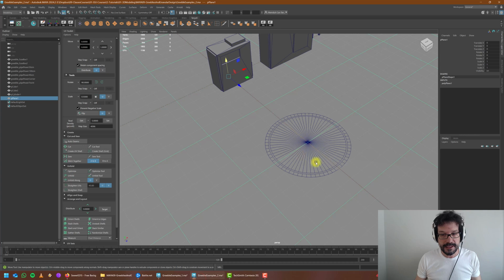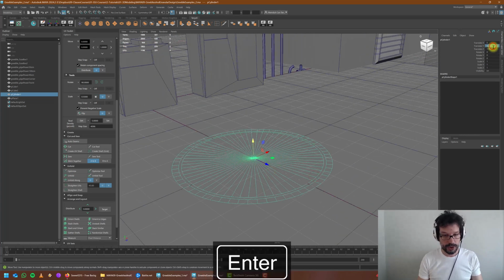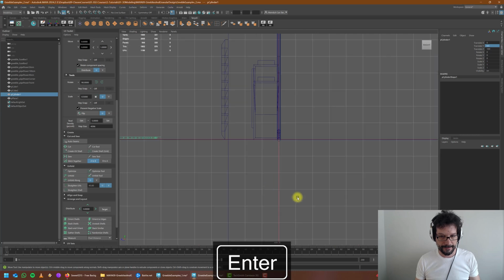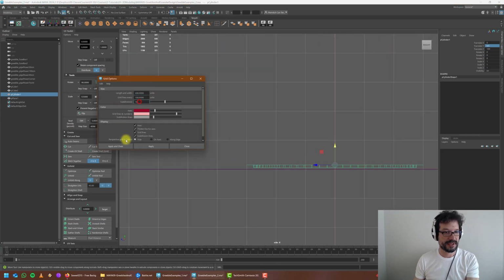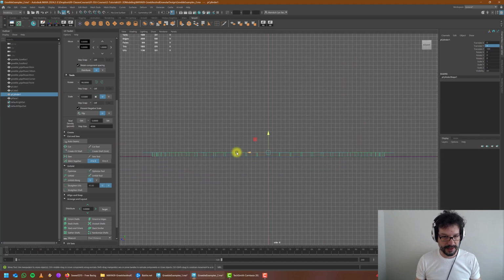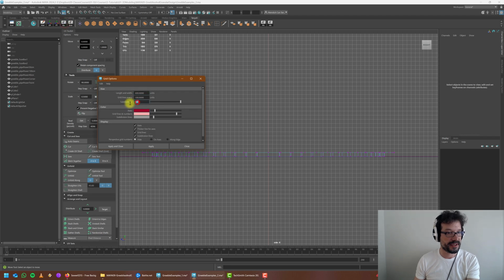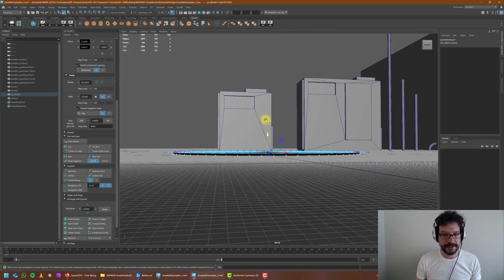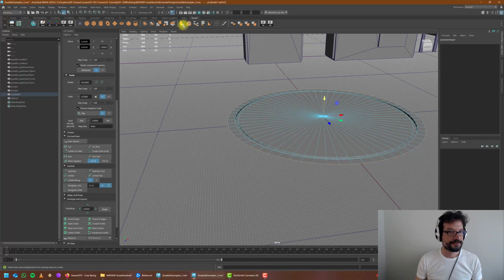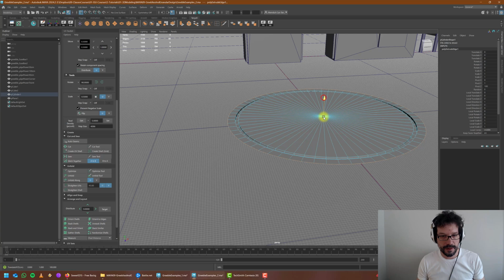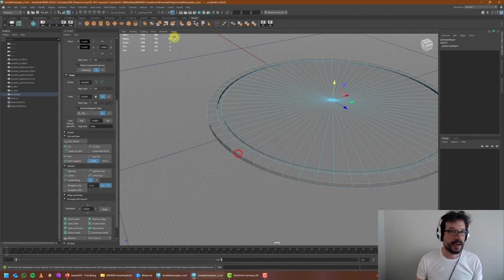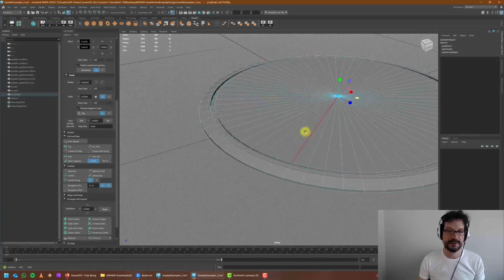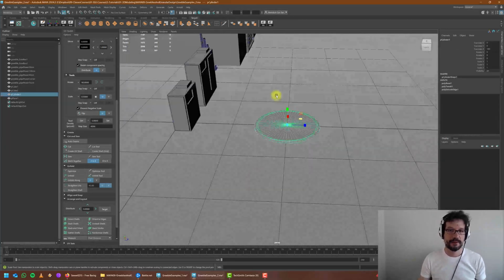So in that circumstance, you can once again exaggerate the detail. Maybe not even this much. Let me just increase the clarity. Let's do just 1 centimeter. Let's even increase the clarity more. Let's go to 5 millimeters. We can do this and even give it a bevel, and then push this area inwards as much as possible to flatten that profile.